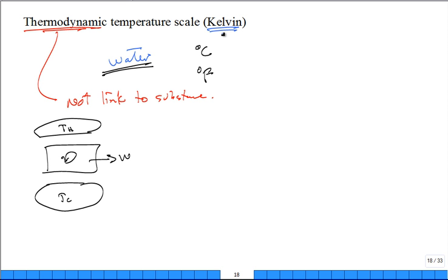He's incredible. So the best I can do is I can say that early on people understood that if you had reversible, everything's reversible in this heat engine operating in a cycle, you would get the maximum efficiency. It would be maxed. Okay? And it depends on TH and TC. If I want to produce heat, if I get a higher heat source, if I burn it with a higher temperature fuel, it'll improve the performance, and they did. Or if they could get it to dump off at a lower temperature, decrease TC, it improved performance, and that's great. So what they found was that the thermal efficiency was a function of temperature hot and temperature cold. So far, so good? Perfect.